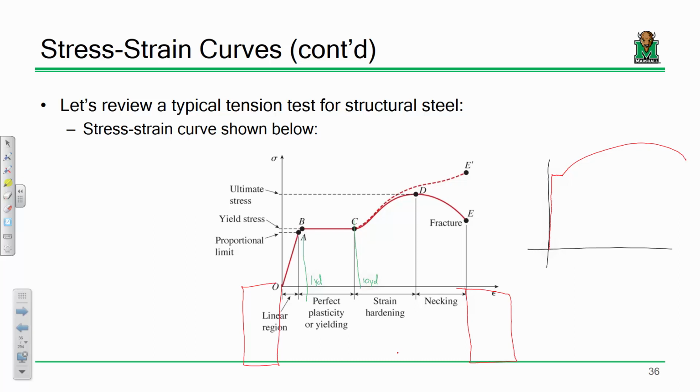One of the things that's nice about using steel in engineering applications is that steel is a highly ductile material. Ductility is something I'm going to loosely define now, and I'm going to come back to it later. But steel, in a nutshell, has the ability to withstand a lot of deformation. It can deform quite a bit before it fails, and that quality is a loose definition of ductility. I'll have a more precise one in a little bit, but I want you to keep that in mind. It's one of the reasons why steel is so commonly used in engineering.